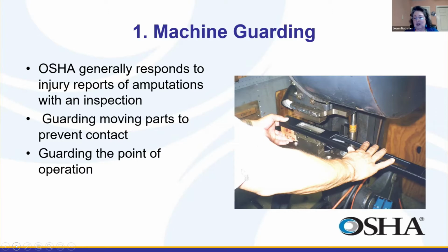So from OSHA's standpoint, looking at the picture, it's like, where is this thing chunking out that piece of metal, and where is the guy's hands? Okay. You shouldn't be able to put your hand where the operation is. So we got a problem there, that it should be guarded. That area should be guarded, so you can't stick your finger in there when the machine is cycling. Okay. So in that case, that's the point of operation.